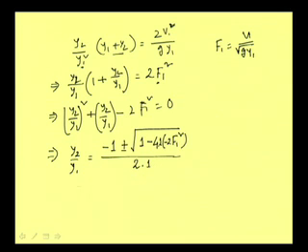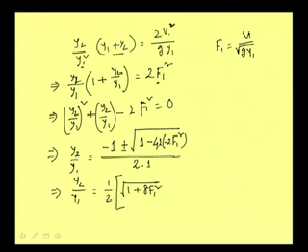So, that can be written as y2 by y1 is equal to half, which we are bringing here, and then this term I am writing first, root over 1 plus 2 into 4, so minus minus plus, 8 Fr1 square. And then out of this plus minus sign, we will have to use the plus sign here. We cannot write plus minus.